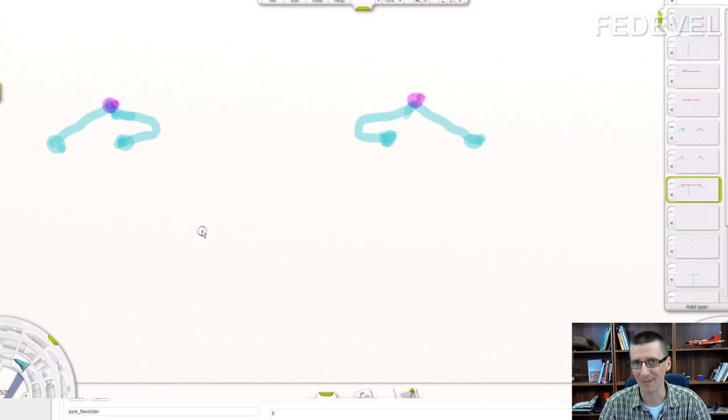Okay, it's not perfect, but you understand, yeah? Length from this path to this via is exactly same as the length from this via to this path. And it is exactly same as the length from this path to this via and from this via to this path. It's very important.